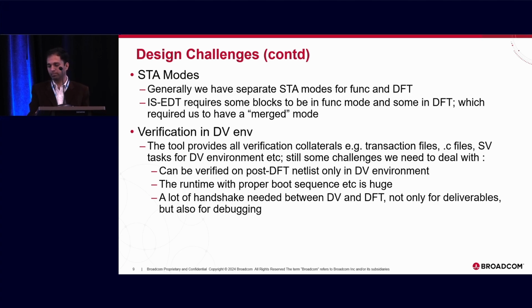And another problem which we faced was that verification of this thing is to be done only in the DV environment. When I say DV, it is the functional verification environment. So all the collaterals are provided by the tool. We have whatever we need: transaction files, C files, SystemVerilog tasks, everything is there. But still, we are running scan patterns in the functional verification environment, which generally we don't do, right?